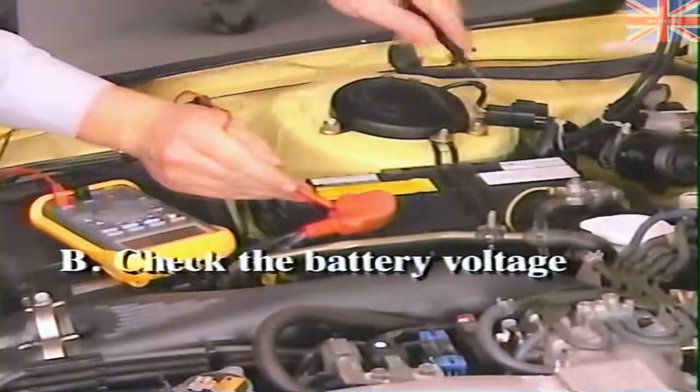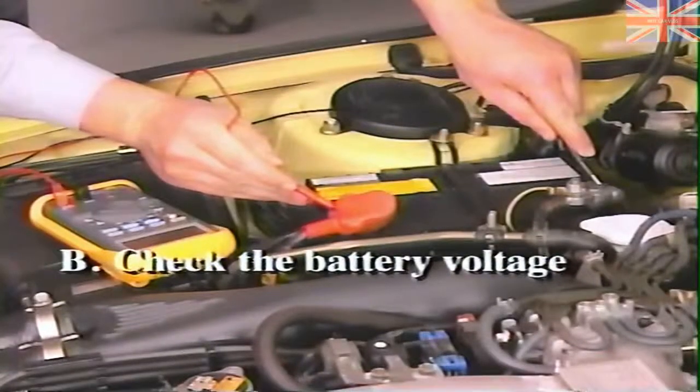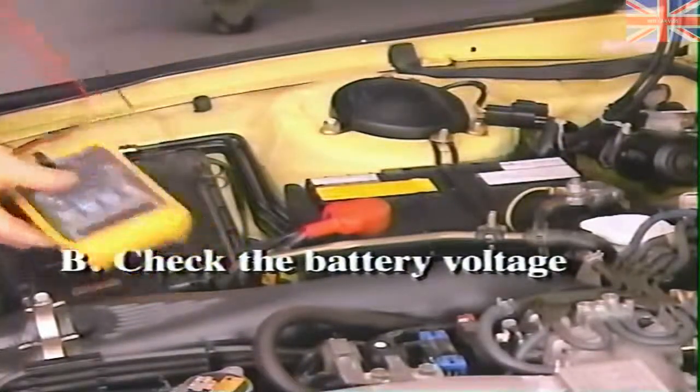The answer is B. Be sure the battery is fully charged. Codes 41 or 42 could be caused by low battery voltage.